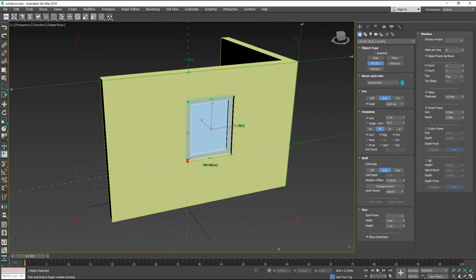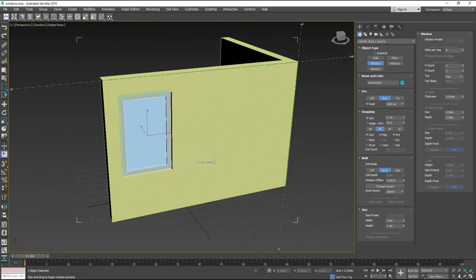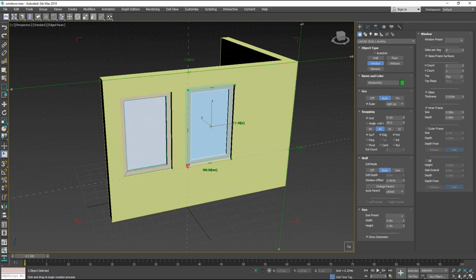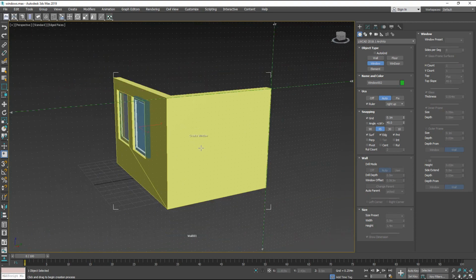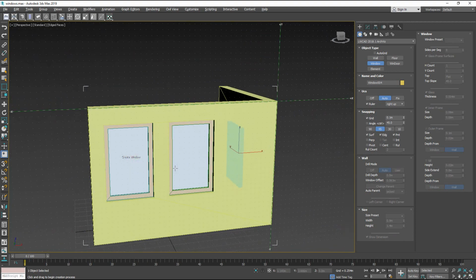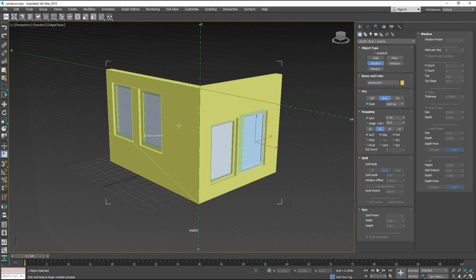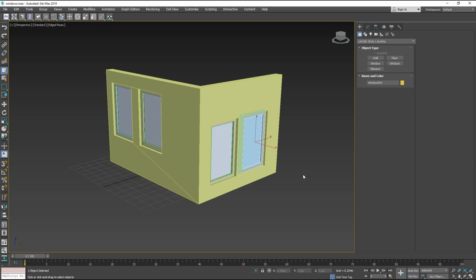And the last very useful thing is this fix button. With the fix button you can, let's say, adjust this window to some size, and after fixing it you keep these dimensions. So with any other click or creation of the next window you keep these dimensions and you just position the new window into the right position where you need it. So as you can see, these helpers and snapping options make placing windows on the wall very easy, quick